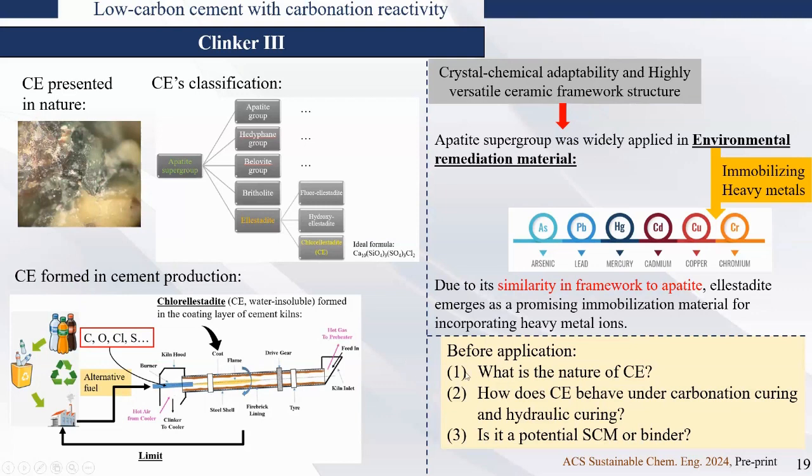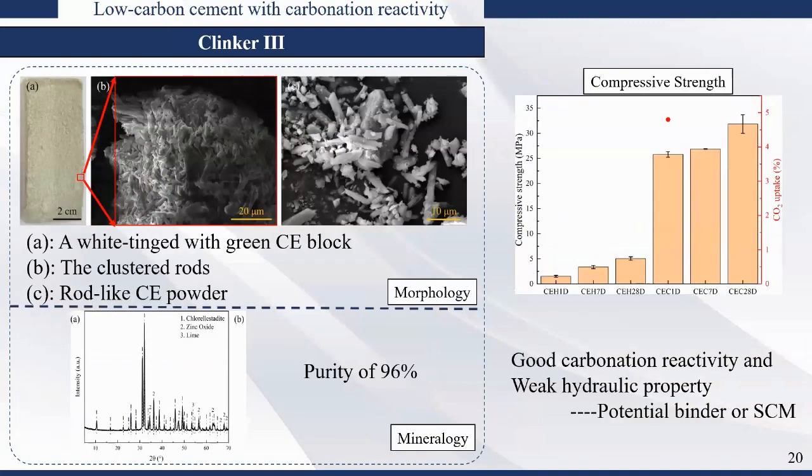So before application, there are several questions we asked ourselves: what is the nature of CE? How does CE behave in carbonation curing and hydraulic curing? Is it going to be a potential SCM or binder? So we synthesized CE in the lab. We synthesized a pure CE. It has longitudinal, rod-like crystals. The purity of the CE we synthesized is higher than 96%.